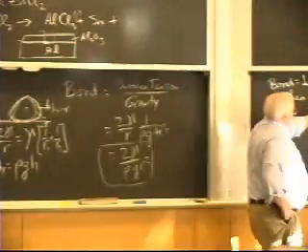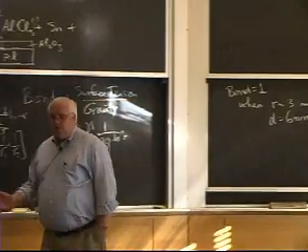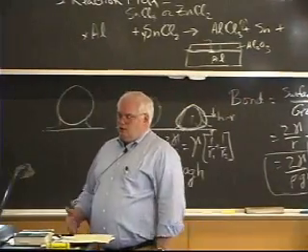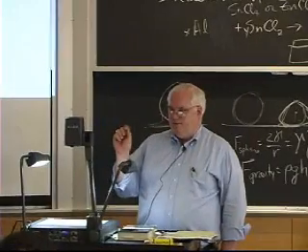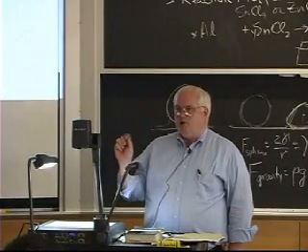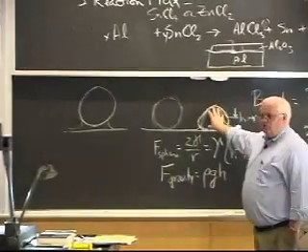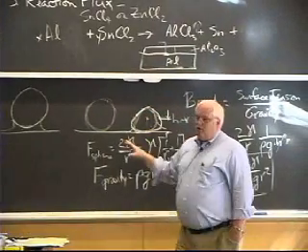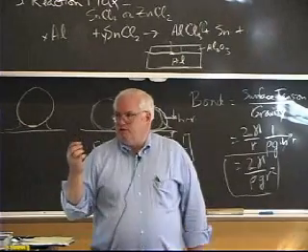Even if the bond number is a tenth, which would be the case if R is 1 millimeter, since it goes as R squared. So if I've got something a couple of millimeters across, then gravity has a 10% effect and the thing is going to slump like this to a certain extent. If I get much smaller than a millimeter, then everything is just going to naturally form a sphere.